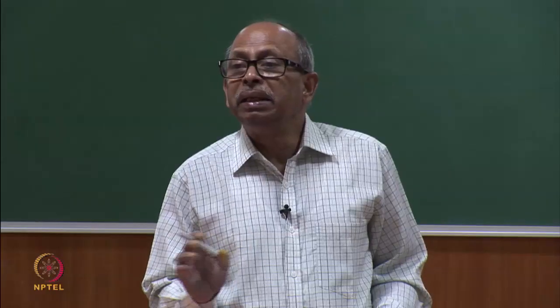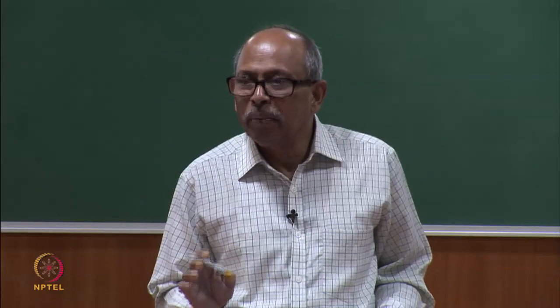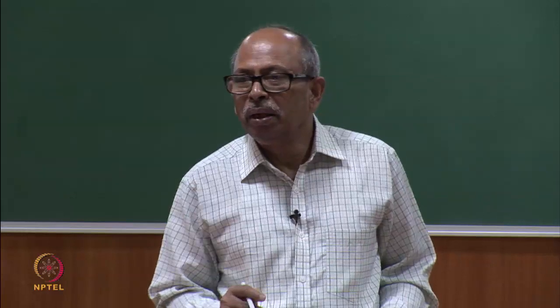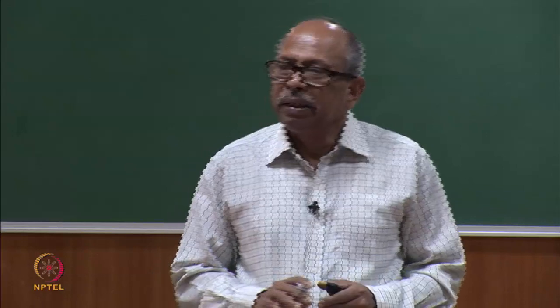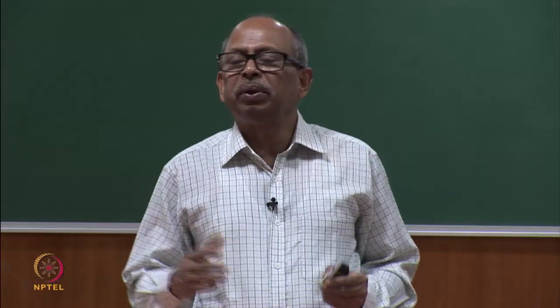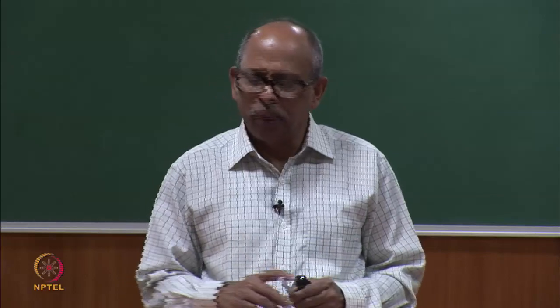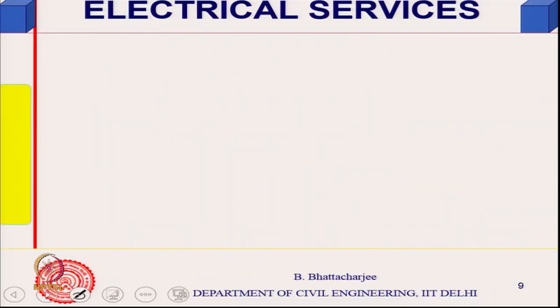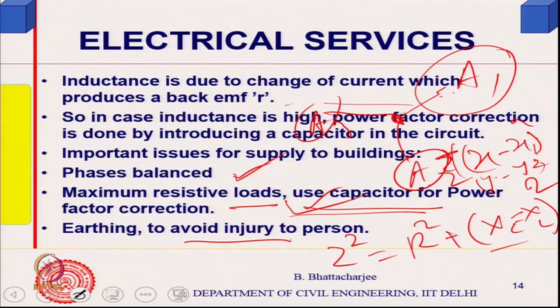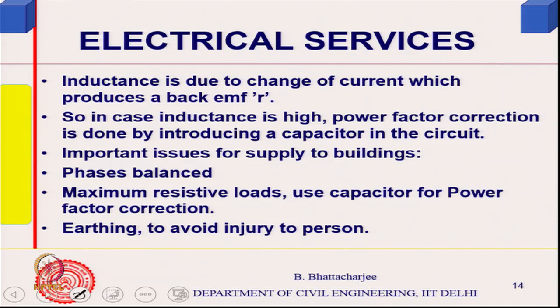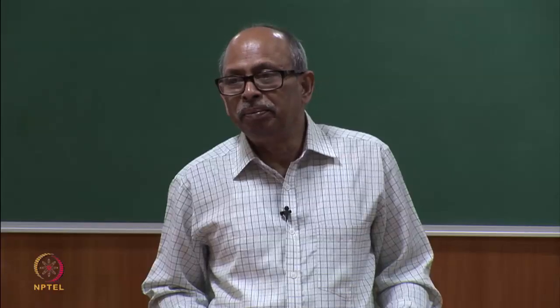That will give you the least cable requirement and cable cost, because the cable size will depend upon the amount of load. So, if you minimize that, that means cable sizing, unless of course they are all similar, then there is no problem, you can just put it at the center or where space is available at the site. So, the substation should be located at the load center, the centroid of the whole area you are dealing with. But in a multi-story building, it usually has to be at the ground floor level above HFL.